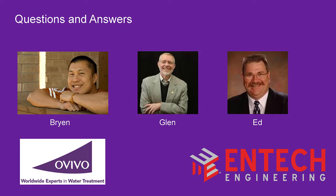You go out there and measure the DO on Monday and keep your conditions kind of the same, you don't have to go checking it every 4 or 5 hours. You check it once or twice a week, and it probably isn't changing. So the trade-off, in my mind, with the instrumentation at some of these smaller plants is check it periodically to make sure your air settings are putting enough in.